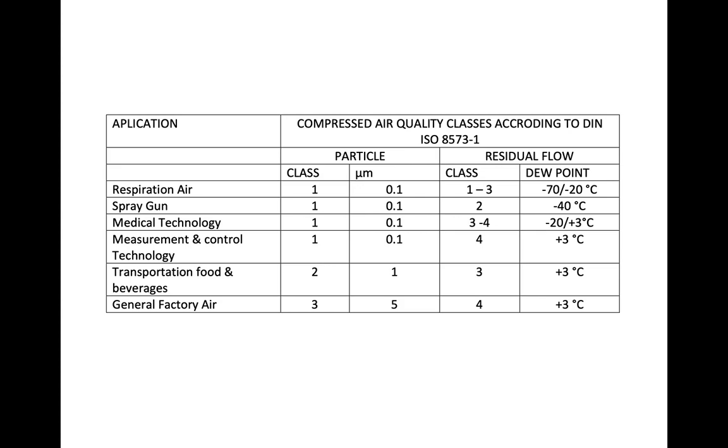It means the maximum dew point is minus 40 degrees Celsius. So this application has a low tolerance to the water content in the compressed air system.